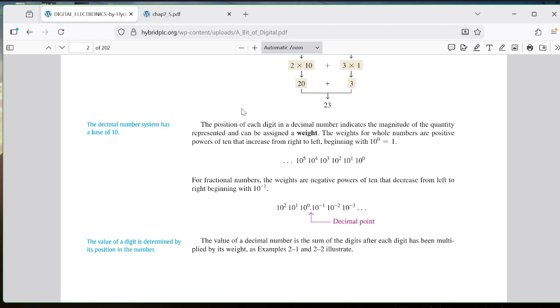And there's also a procedural language. It's a C-type language or a Python-type language. It's just a flowing, top to bottom, looping language that you can use as well. You pick which one, and you can have all three going at the same time. There are other languages as well, and we talk about them sporadically, but there's at least two others. So one of the goals is not for you to be so proficient in ladder that you forget about all these other languages, but to be able to pick which language is the best for the application, and you work accordingly.